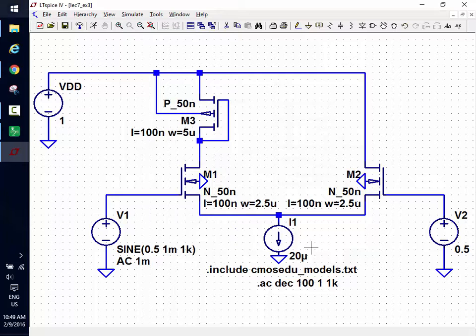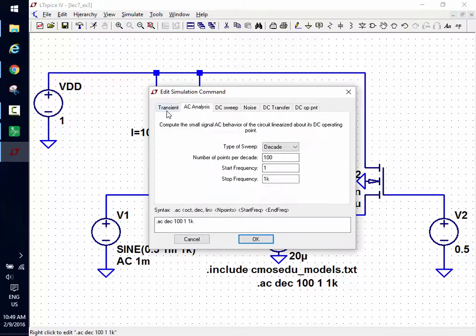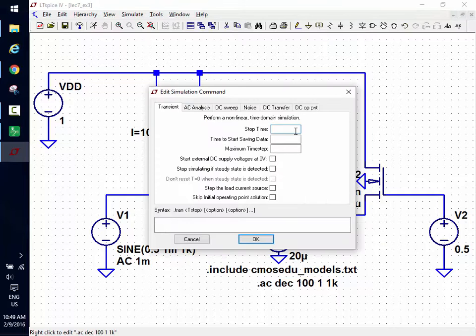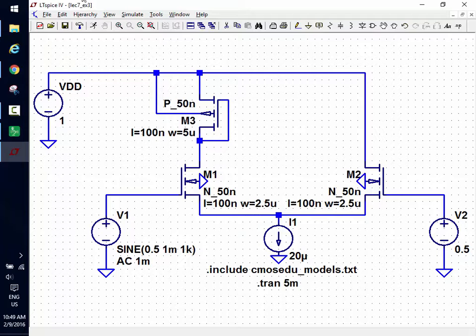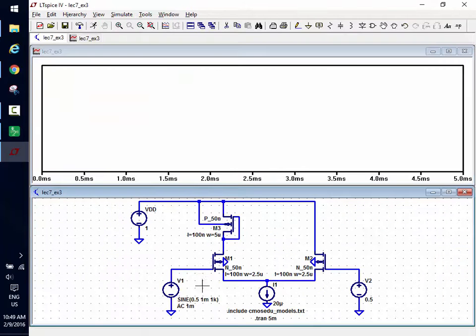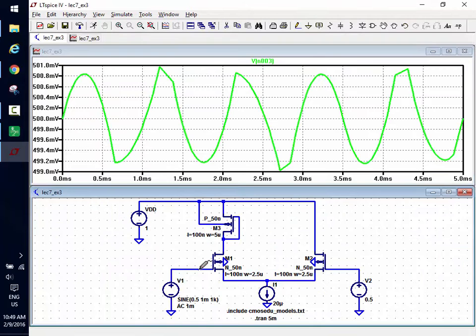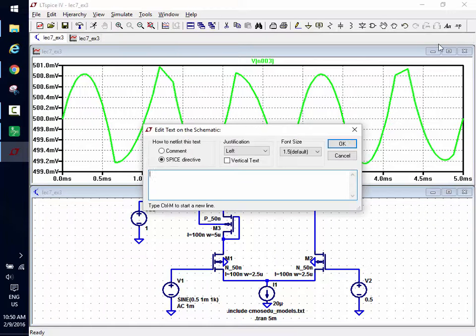All right. And then what do I do next? Change it to .tran. Let's stop time, let's do 5 cycles. What am I guessing is going to happen this time when I run the sim? It's going to be jagged. I didn't put the .options plotwinsize=0 in there. Let's see what happens. Hit run. Nothing succeeds like success. Oh, no. Let me waste a half hour on that.